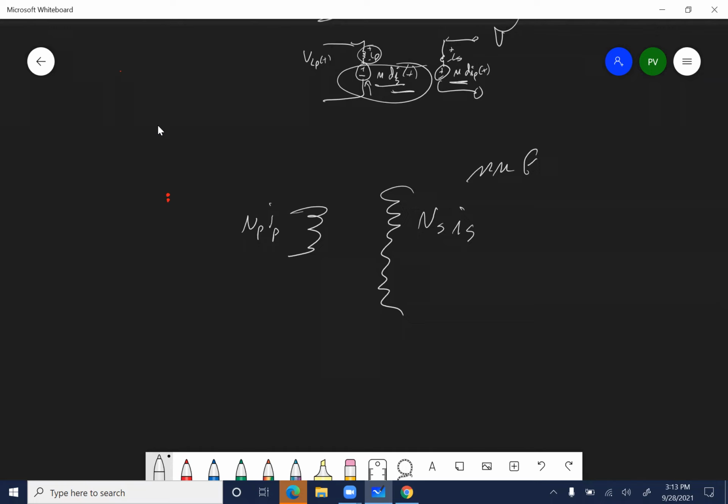But normally you would take a piece of steel. If you really wanted to try something, go to Home Depot and buy a couple of steel washers, 5 or 6 larger ones, and glue them together with some sort of thin epoxy. Then let it dry and wrap one side with a bunch of magnet wire, and then go completely on the other side, not touching at all, and do the same thing. And you just built a transformer, because the washers are usually made out of steel. So that would not be a terrible transformer.